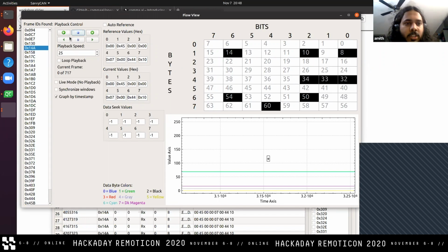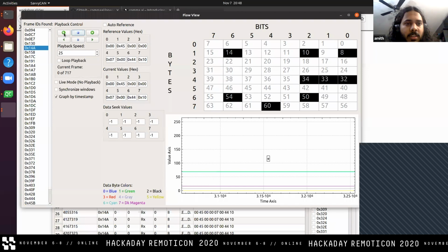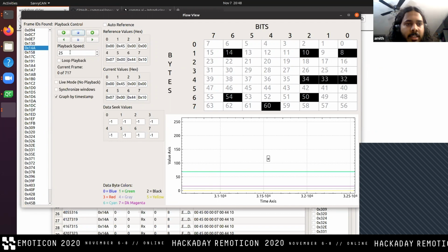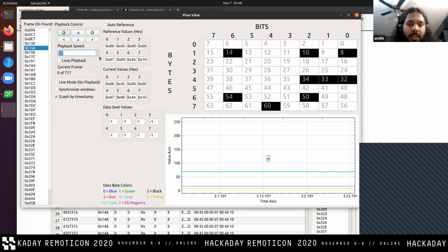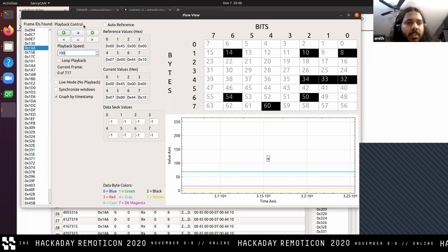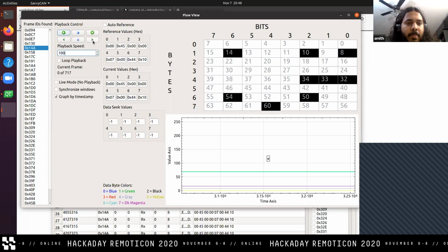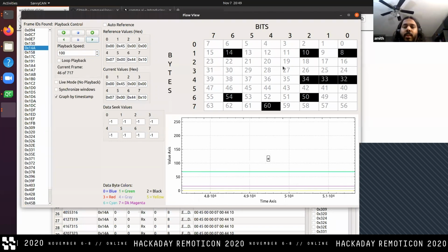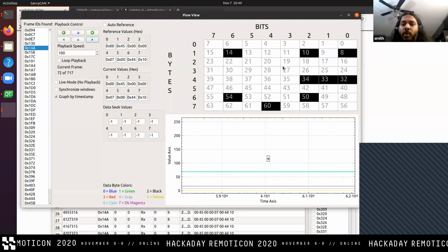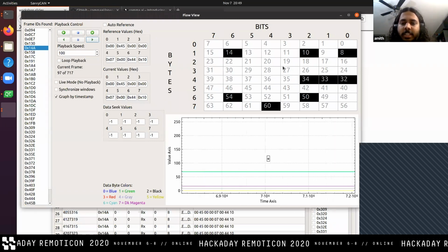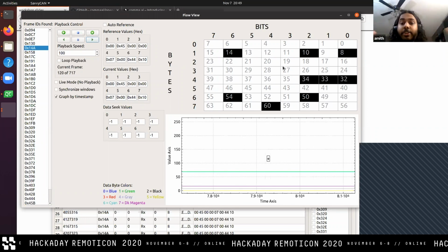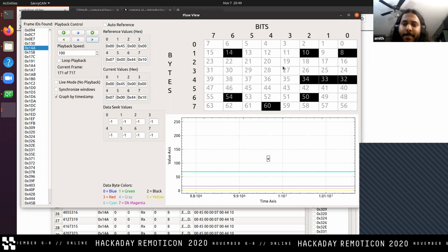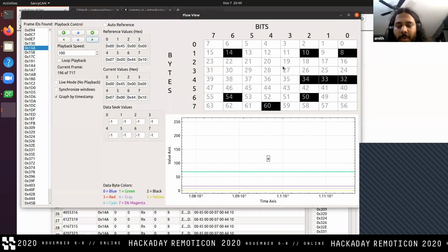So if you guys notice, let's just start from the first frame. Then I'm going to play through it. I'm going to slow down the playback speed to something that we humans can keep up with. So let's say 100. So I'm going to play it. And notice how it's very still. So I first recorded it while not moving the wheel. So the steering sensor has no reason to input anything in a neutral position. And you notice that when it goes crazy, that's when I'm turning it one way and the other way.